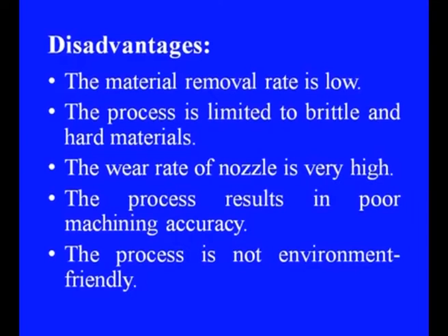Let us also look at the disadvantages of this abrasive jet machining process. The process, as we have already discussed, is basically a finishing process or low level cutting process. Therefore, the material removal rate in this process is usually very low. And as I have already indicated, the process is also limited to brittle and hard materials.